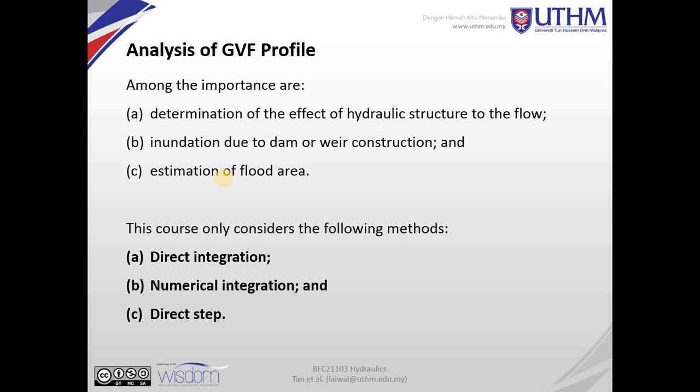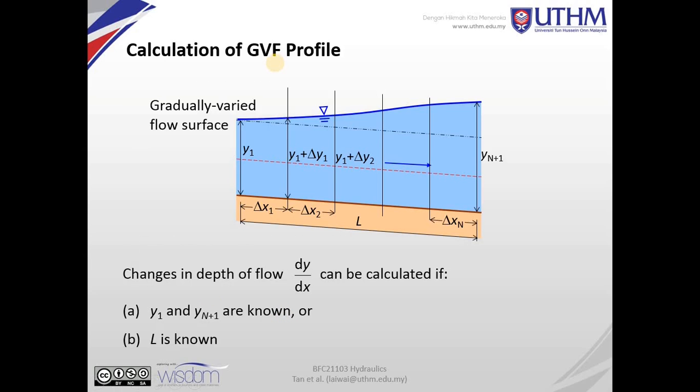So this course considers the following methods. There are several techniques in estimating or calculating the GVF flow profile. However, in this syllabus, in your undergrad syllabus, we are going to learn three methods, which are the direct integration method, the second one is the numerical integration method, and the last one is the direct step method. In the GVF profile calculation, the change in depth of fluid dy over dx can be calculated if we know two parameters out of these three parameters.